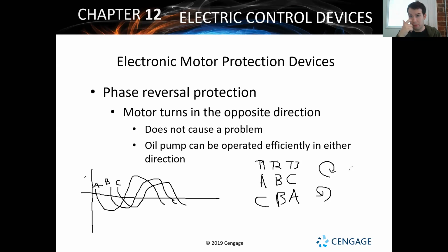Basically, the motor going in the opposite direction is going to cause the system to not operate properly. Now, your unit might not get damaged. You might have it where you can deal with it. It might be okay for a little while, but you're going to have a lack of heating and cooling.